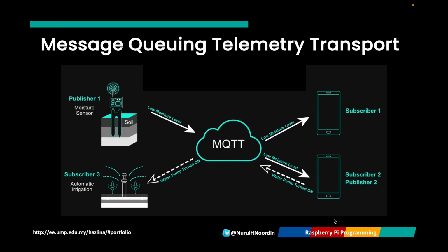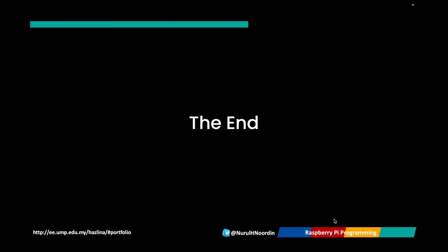The Raspberry Pi Pico collects sensor data such as temperature or humidity. The LoRa module transmits this data as a LoRa packet over long distances. A nearby LoRa gateway receives the data and forwards it to the network server. The server processes the data and sends it to an application dashboard or cloud storage for further analysis. By using this setup, IoT devices can reliably send real-time data to cloud-based platforms without requiring high power or expensive cellular connectivity.